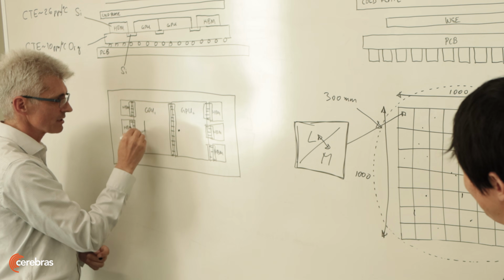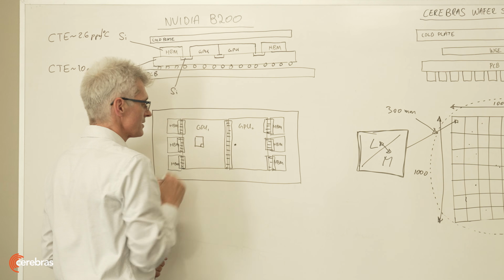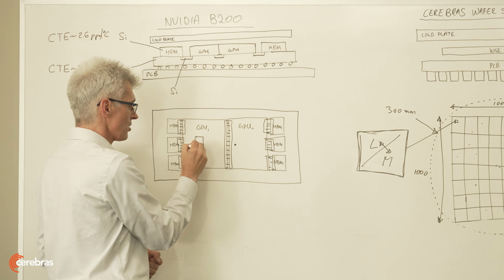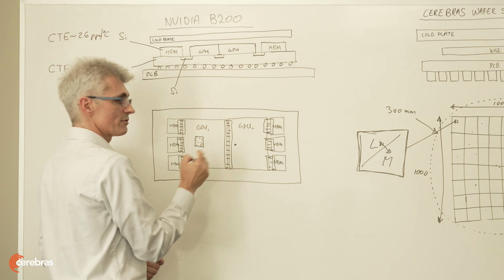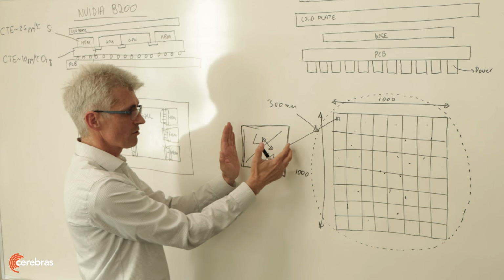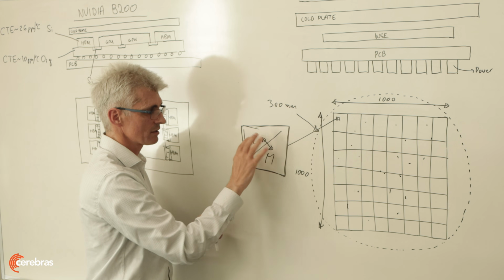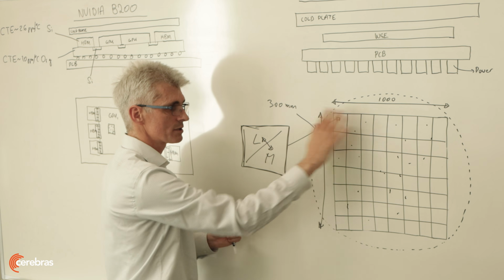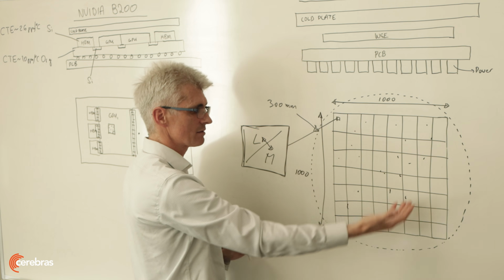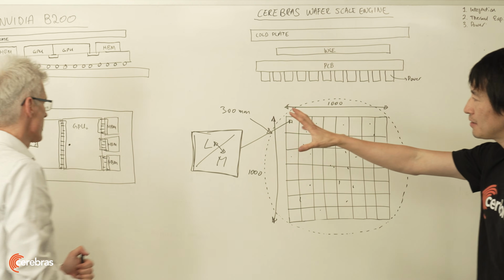because the cores there are bigger than our core, which is relatively smaller, if you have failures, that core needs to cope with many failures that for us would just be one of the cores being defective. If it is defective, we can logically remove it from the array and abstract it from the upper layer software, and software can see this entire wafer as being a perfect wafer. That's great. Let's get back to this.